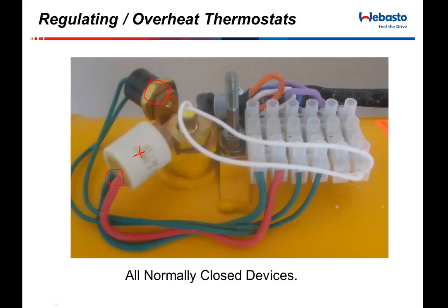The third product that's underneath this black cap is a double white wire which ends up onto what I'm going to refer to as a melt fuse. And this melt fuse is wired in series with that double green overheat thermostat. That fuse is put in there basically to detect air.